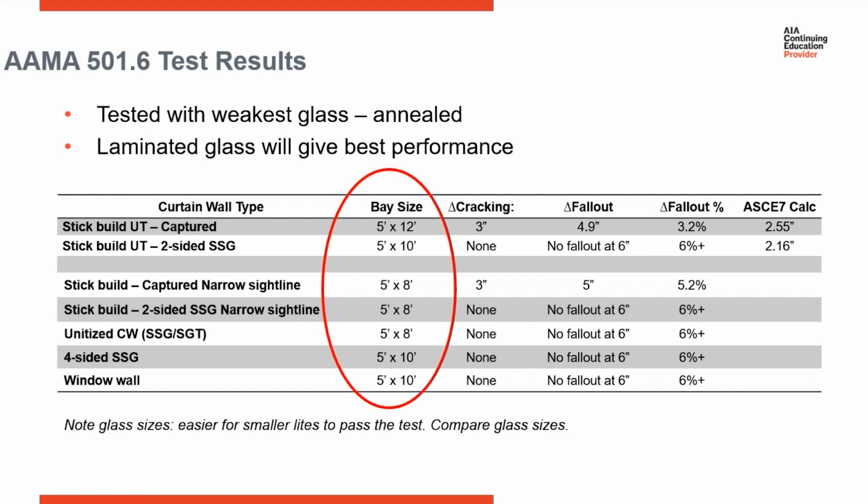Also note the base size. So in general, just always pay attention to the base size. The smaller the glass is, the more movement that you can accommodate. So make sure that the glass size in the test report matches or is bigger than the glass size for your project.